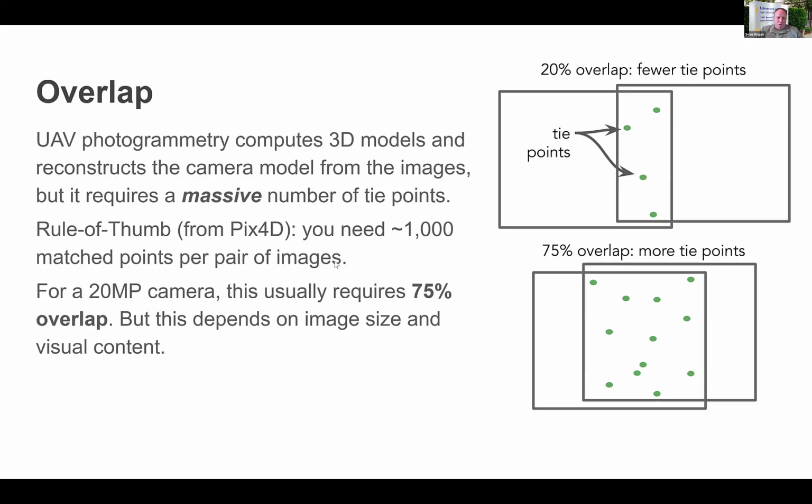For Pix4D, there are not a lot of best practices reported on ESRI sites that I could find. In fact, there's very little in the way of to-the-point tutorials on how to use Drone2Map, for some strange reason. Usually you see a lot of video tutorials out there for applications, so I sometimes refer to Pix4D's standards, which are basically going to be the same. And they note that you should have roughly around 1,000 match points per pair of images to really connect them together for a good orthomosaic and photogrammetric processing.